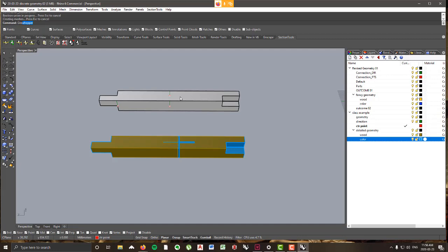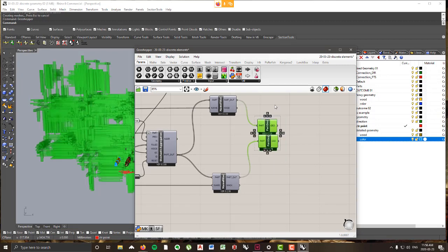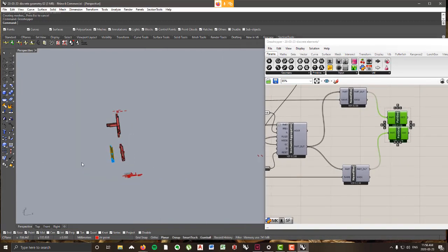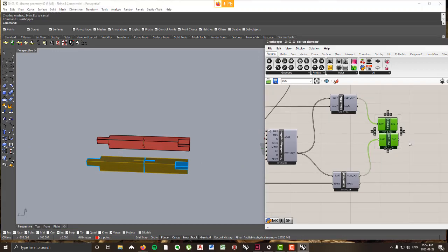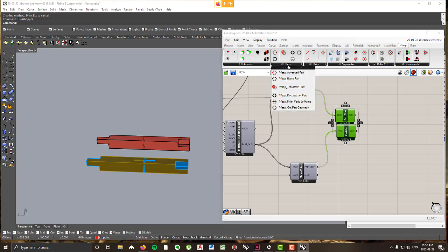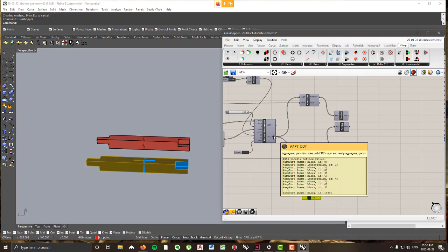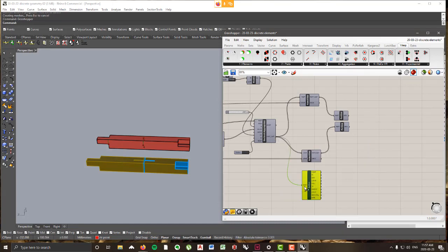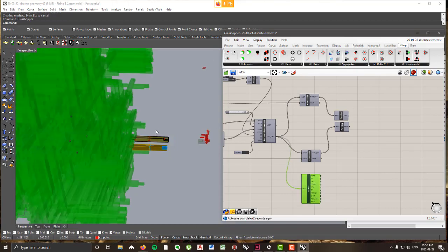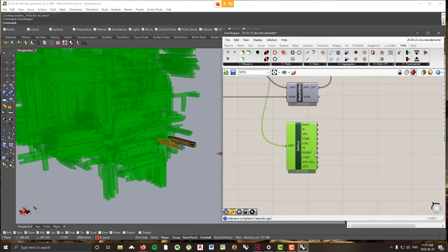So what I'm going to do is go into Grasshopper again. I already have this array here. I'm just going to preview it off. And essentially what I am going to do is go to wasp, and then parts, and then wasp deconstruct part. So wasp parts, wasp deconstruct part. The part out of my aggregation, I'm going to put into the part in of deconstruct parts. Again, it's giving me the geometry, but the other thing it's giving me that's really interesting is the transform.